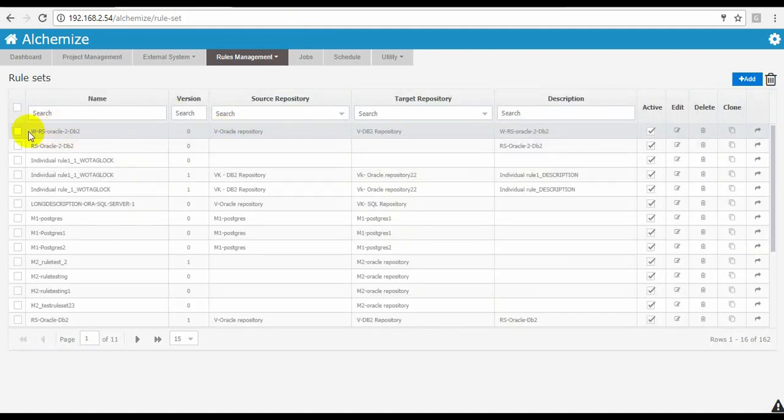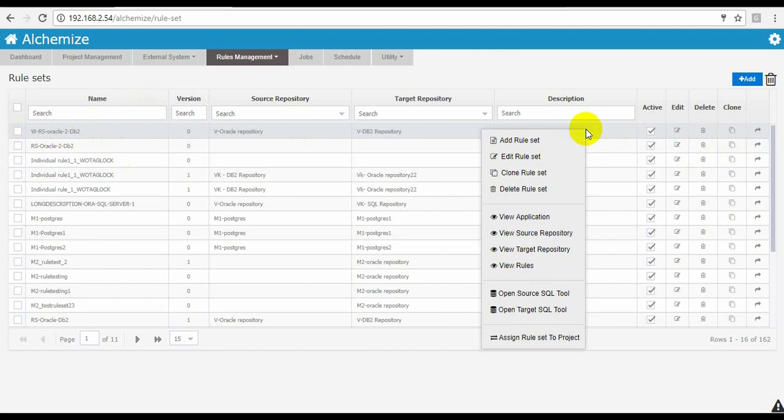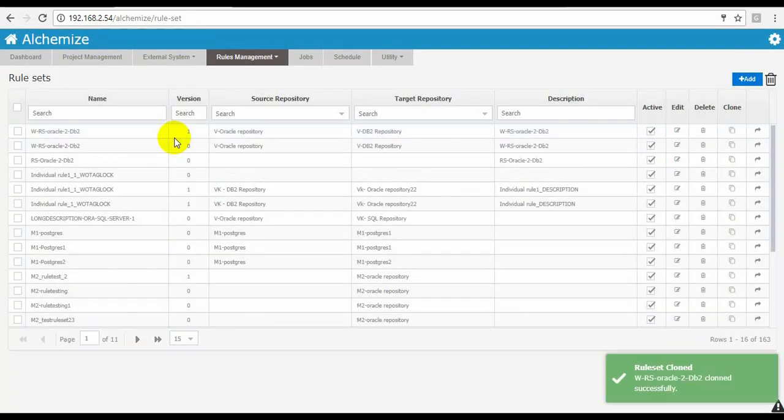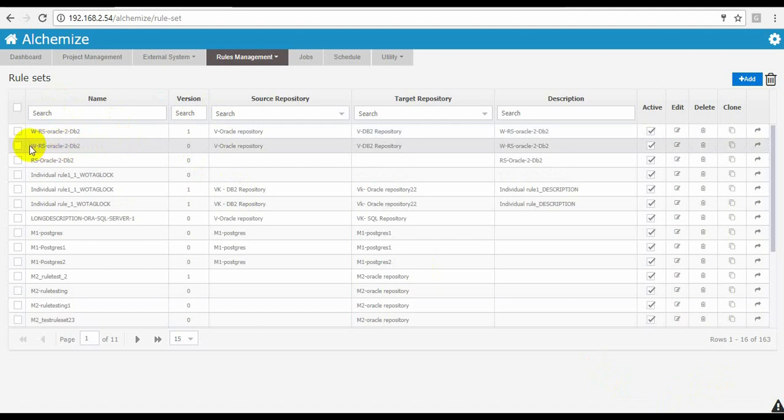Additionally, in the Rule Set section, you can click on your new rule set and can clone the rule set. Also accessible in the context menu by right-clicking. And you can duplicate this rule set. Click Clone, and now your duplicate clone pops up on the Rule Sets page as well. The version will be different, so you can have the ability to differentiate these rule sets.